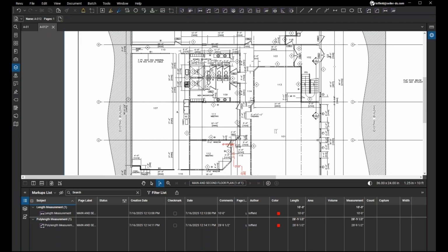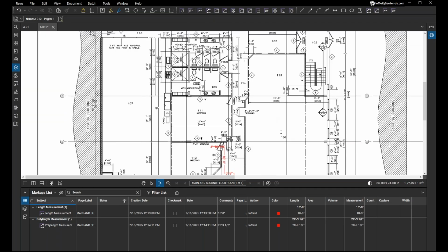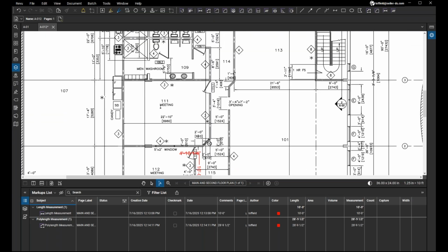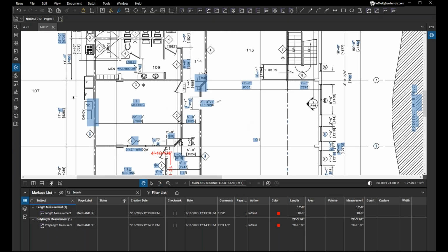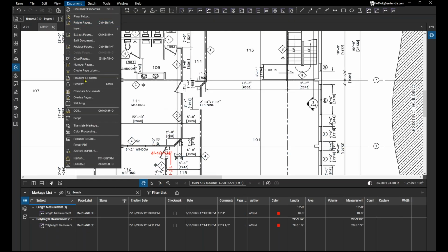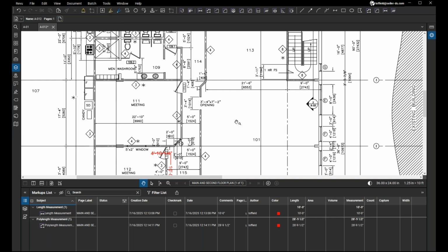But if it were the case where the CAD designer were to export a PDF for you and you not have access to that text immediately, fear not, we do have that OCR command, and that is also, like I said, right here, found in your document menu. Control-Shift-O for the fans of the keyboard shortcuts. Bluebeam Revu has a lot of those, so if you're a fan of those things, that would be pretty handy to start memorizing.